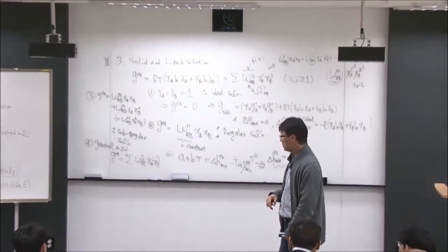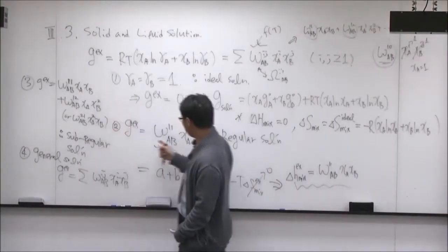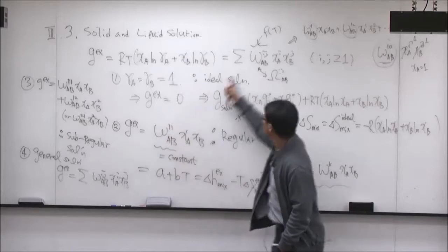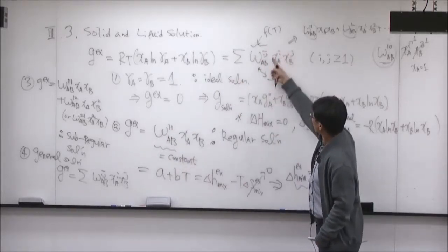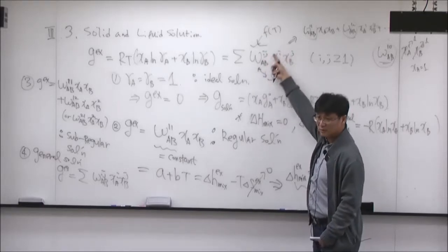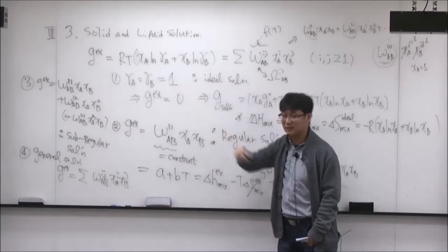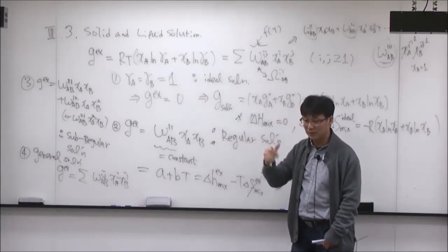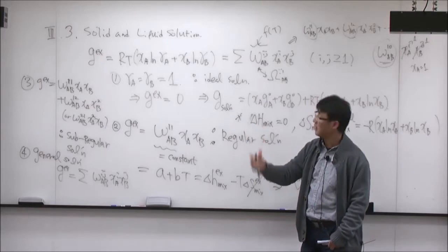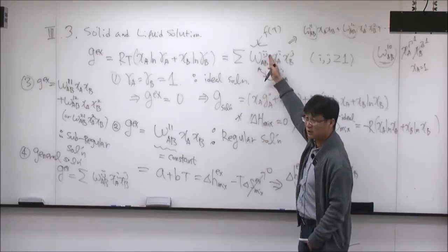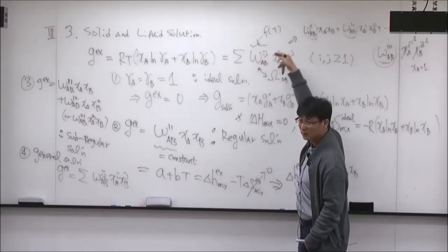So omega can be dependent on composition in this case here. Omega itself, as I mentioned, is only a function of temperature because the composition dependence is expressed here. This Gxs parameter is temperature and composition dependent. And that actually splits into two in this expression: one is the temperature dependence term and the other is the composition dependence term.